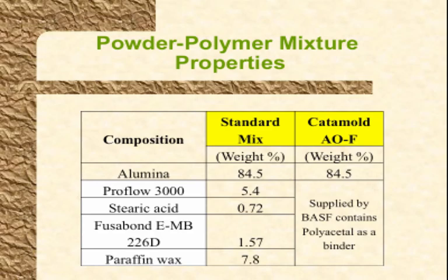So let's say you have alumina in this type of a polymer combination. You have an ethylene propylene copolymer. You have another grafted copolymer of propylene and maleic anhydride. We said grafted polymers, one part binds to the powder surface, the other part combines with the polymer, so you can have better strength or better uniformity in the mixture.